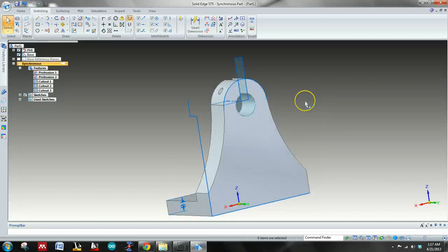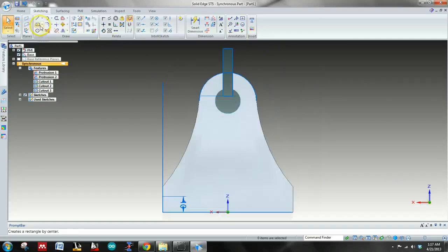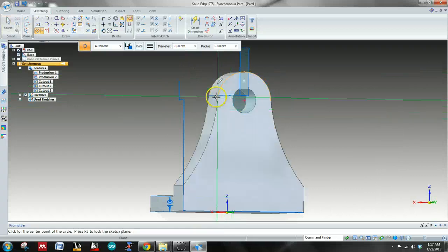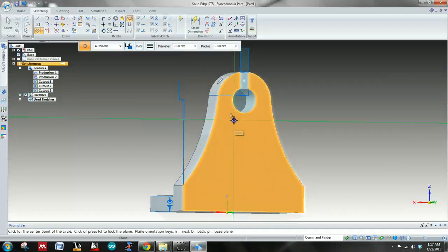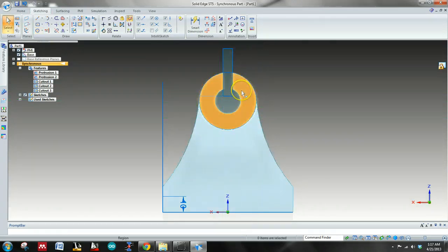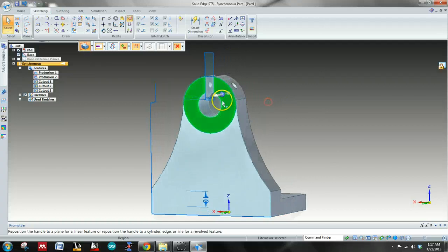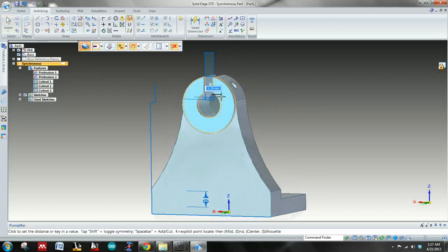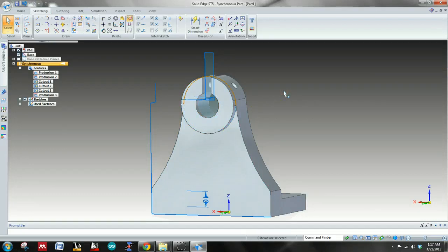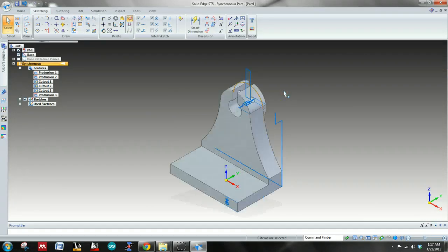Now let's come back, Control K, because now we need to add another circle. We need to add 4 millimeters to this side. So F3, Control K, and again, same sort of thing. We're going to come down here. We have the center. Put it out. Click it, and then hover over top of that arrow, pull that out, 4. Control I, Control F.